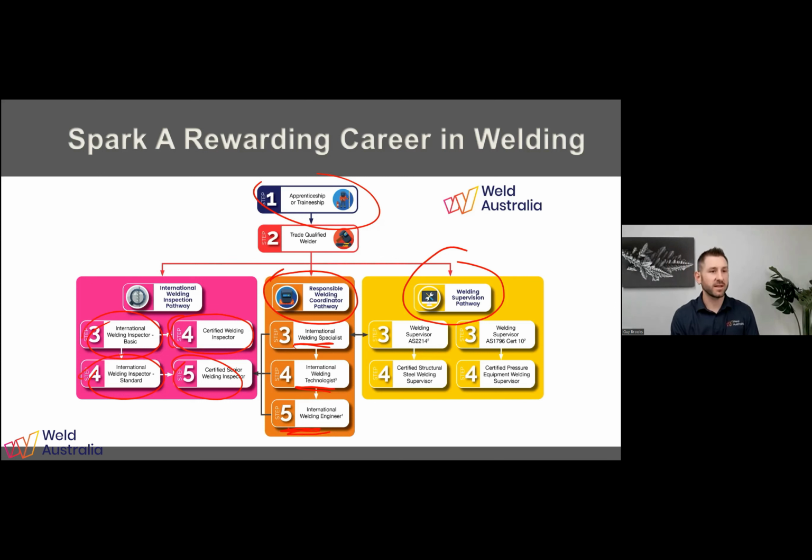So the welding inspector looks at the standard and says, hey, this is to 1554 part 1. I need 10% mag particle, 100% visual, and these 3 joints need to have this or that or the other. So they're the person that coordinates that, right?